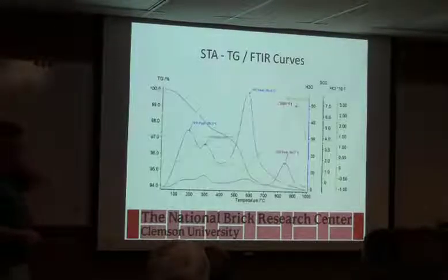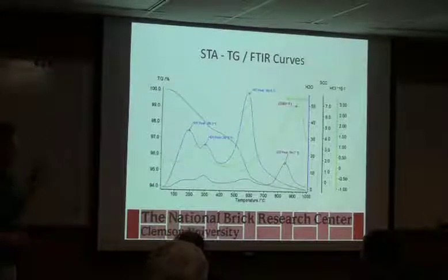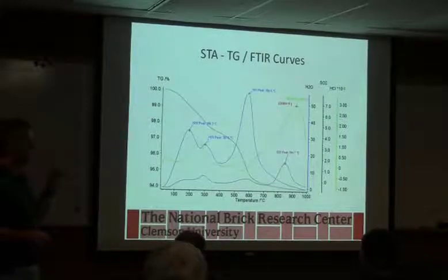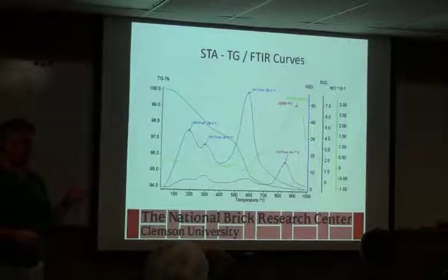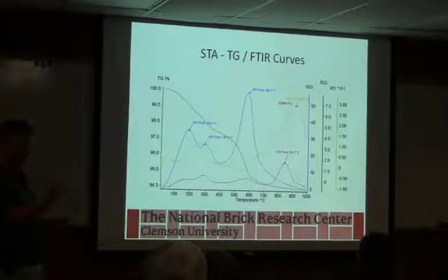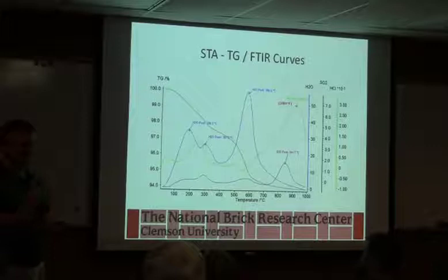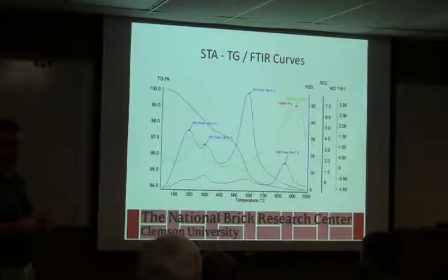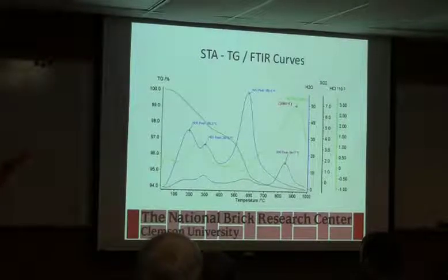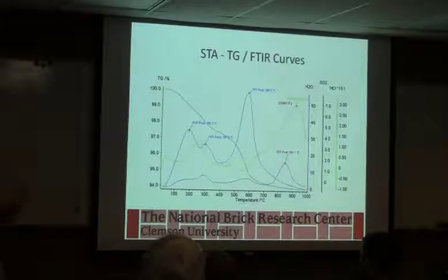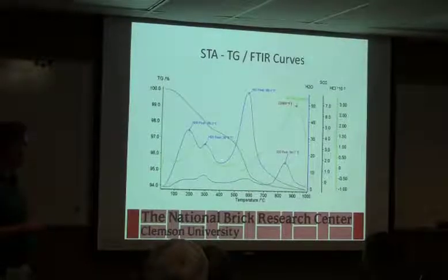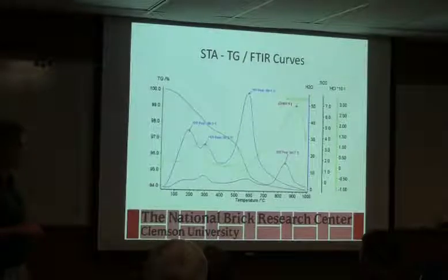One of the things we can look at too is TGA, thermal gravimetric analysis. It looks at weight change per temperature change. It's about the size of a racer, with little crucibles we put material in, and it has a super sensitive balance on it. We put a control sample and your sample on there and look at the weight changes. It gives us peaks, and water change is a big thing.